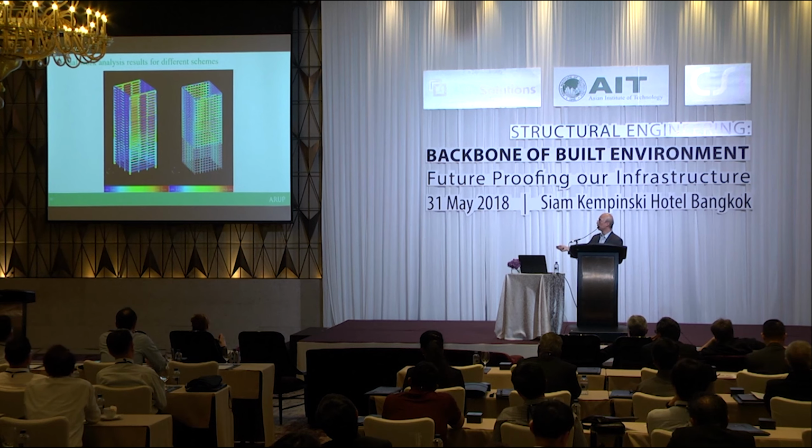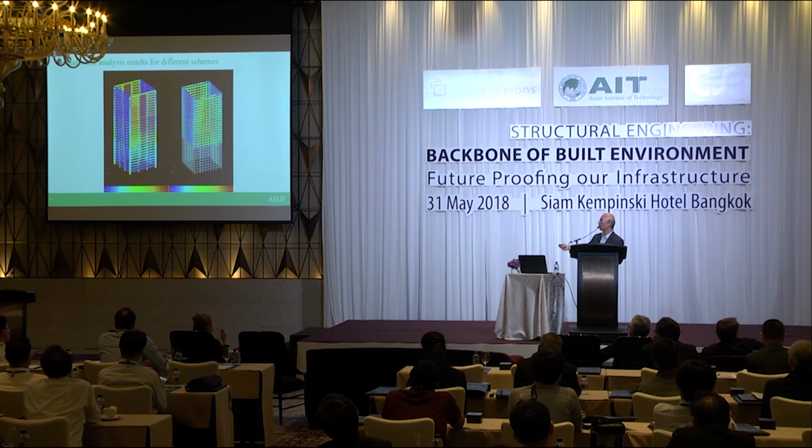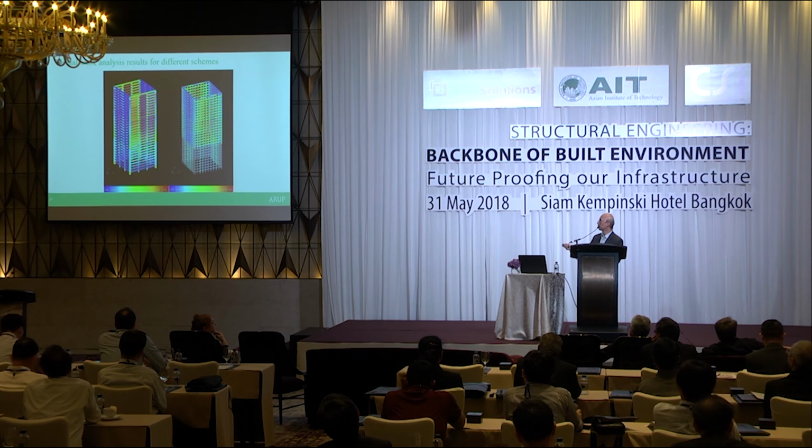So basically it means that this beam, if you make it deeper, it's more effective to control the drift. And for this one, you can make it shallower, it won't affect too much. Of course, we can make more columns, right? And with more columns, the color is more like an average, right? So in terms of structural engineer, I think we'll say this one looks better, right?